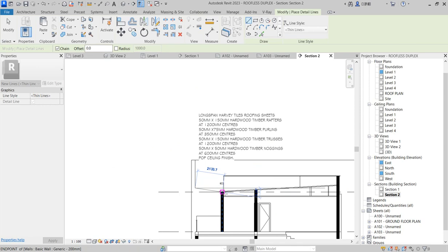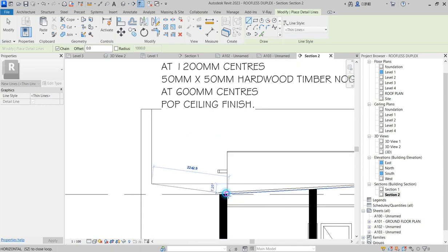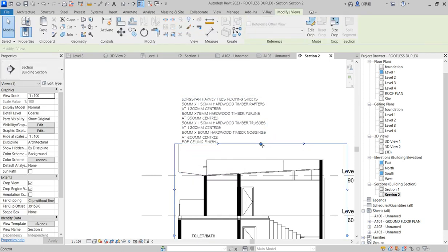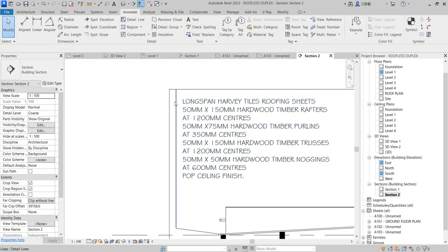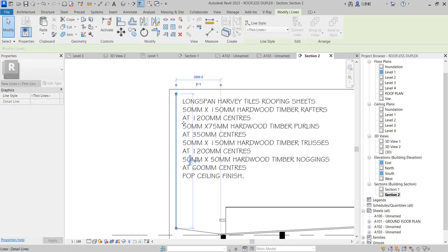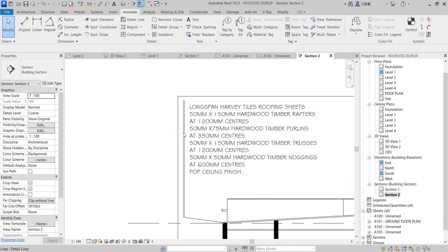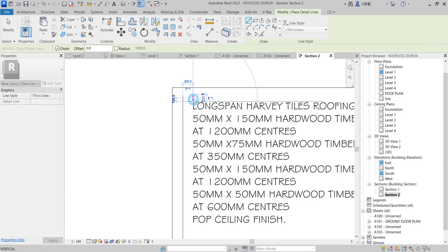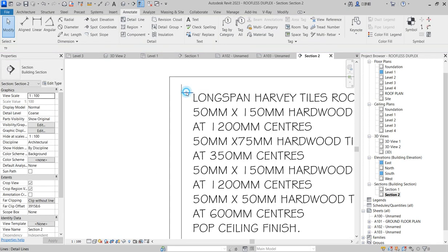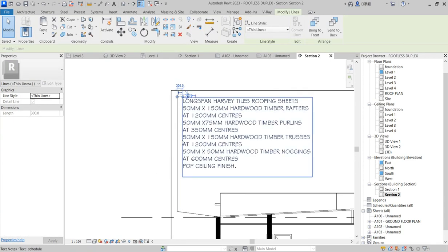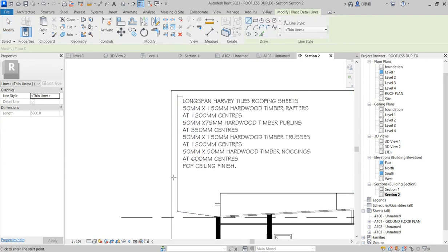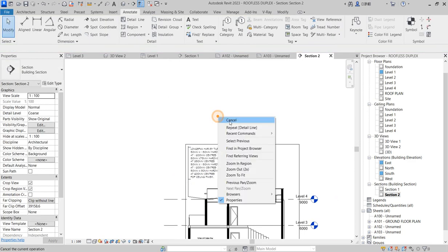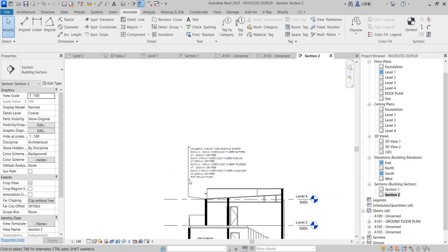all the elements here are recognized by certain rules. So this one will cover up for them. So you select your crop and extend it up so that you'll be able to draw this line across. So that is what we have here, and that is just the little trick that you have in creating section for Revit. If you have any other method that suits you, you can quickly do that. And this is a very quick and fast method when you also want to do submission for a client.